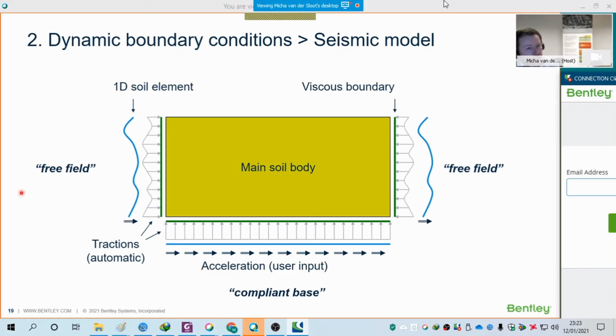So we introduced in Plaxis also dynamics with consolidation. That means during earthquake events, we can also dissipate a bit of excess pore pressure. That can make a small difference in the analysis, while not having sometimes very extreme peaks of excess pore pressures. These are then also reduced during the analysis.